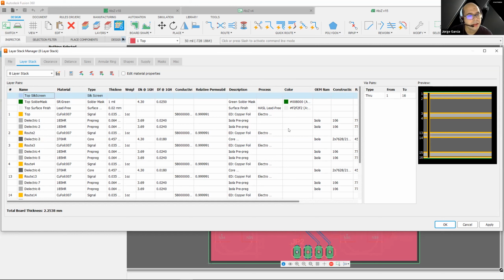Yeah. Okay, excellent. So just a little side note to what Richard was mentioning about the symmetrical versus asymmetrical stack-ups. What we refer to as symmetrical is basically even numbers: 2, 4, 6, 8. What can happen is it is possible to do a non-symmetrical layout, but you generally want to have some very compelling reason to do so.